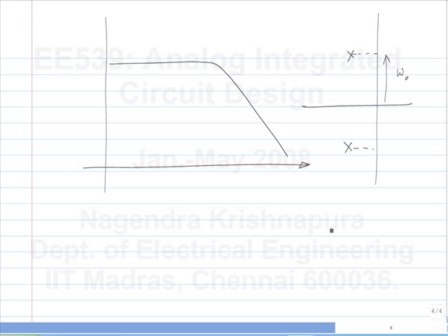So, the way what you are doing is you are trying to somehow, here you know that beyond this point the circuit tends to respond less and less to the sinusoids, okay. But if a circuit has poles like this, if a circuit has a tendency to ring, it's naturally providing some of these frequencies, okay. So, you make it ring slightly beyond this, so that the combination of the circuit's response going down but combined with its tendency to ring will become flat.